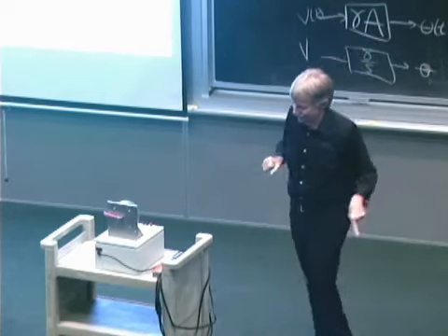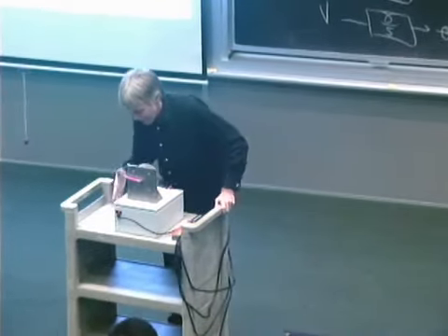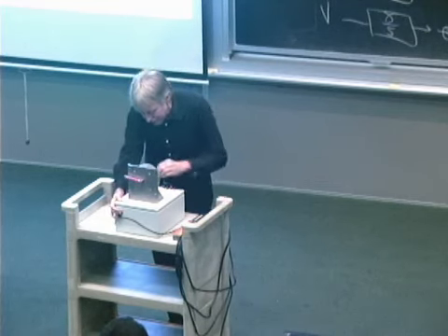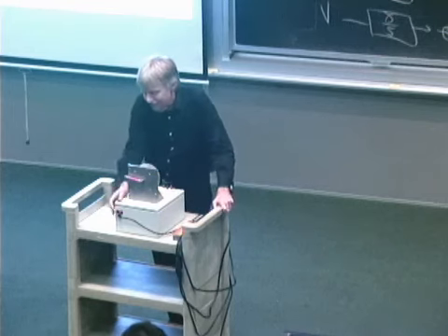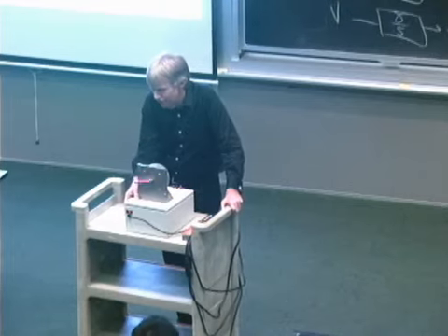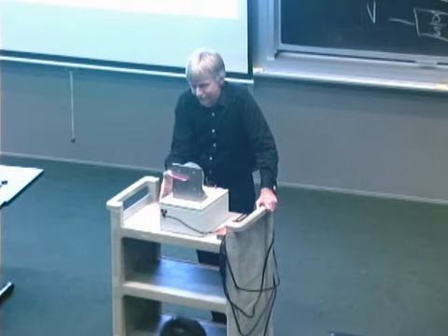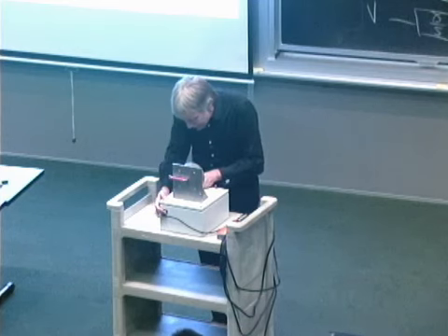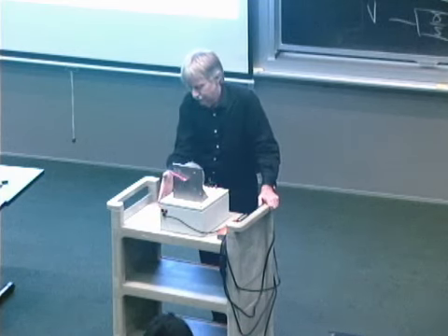There's oscillation, right? Turn it back on, let the thing kill itself. There's an oscillation. Turn the gain down so it doesn't kill itself quite as quickly. It's oscillating. Watch the oscillation, right? Think about characterizing the oscillation. Make the gain smaller.